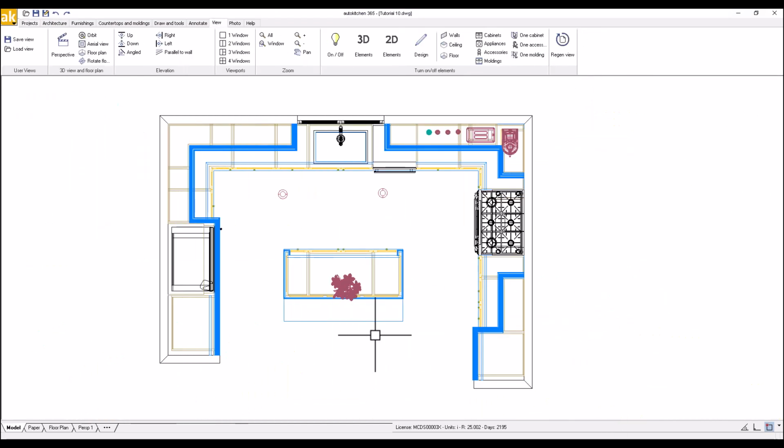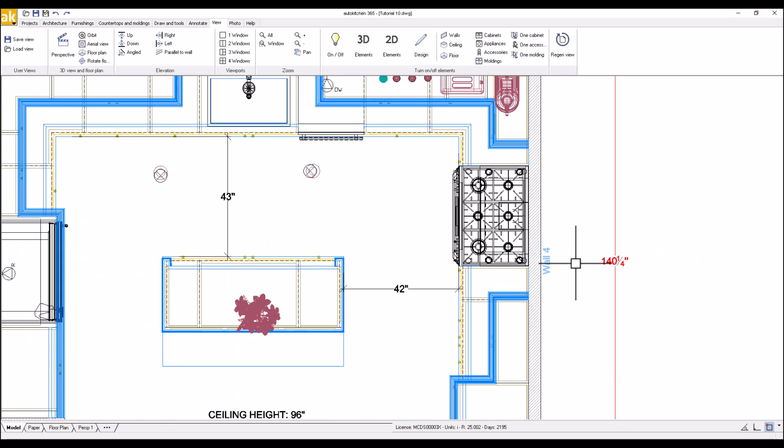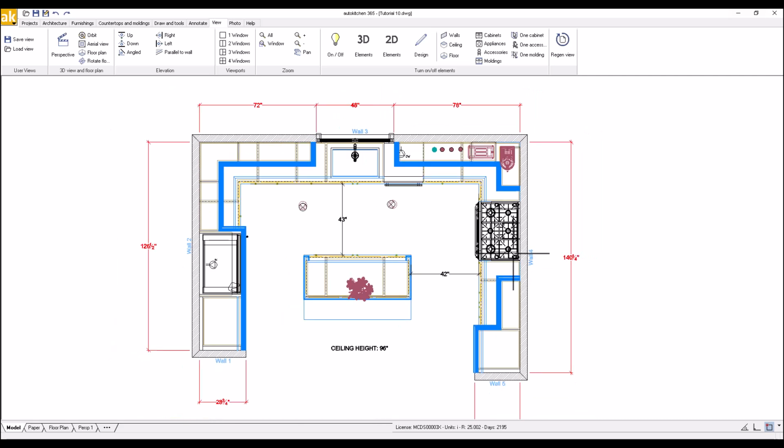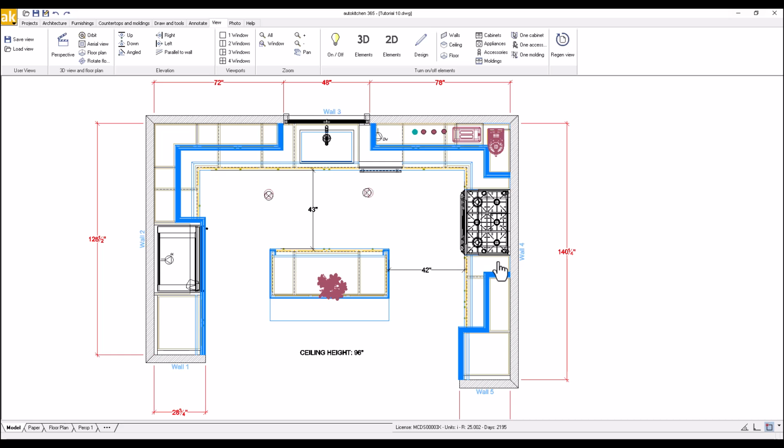Printing elevation views with dimensions. Next, let's print the elevation of Wall 4. Wall 4 is the elevation view we placed dimensions on in Tutorial 8. The steps to print this elevation view are similar to the steps we have followed to print the floor plan and perspective. The only difference is that the elevation view will not be on the screen when we print it. Make sure the design is still in 3D view so that the layers we need are on.